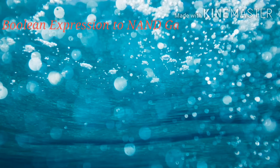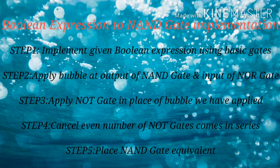Not only NOR gates, but we can also implement NAND gates. There is only one change in step 2, that is, add bubbles at the end of AND gates and the beginning of OR gates. All remaining steps are the same as in the OR implementation.